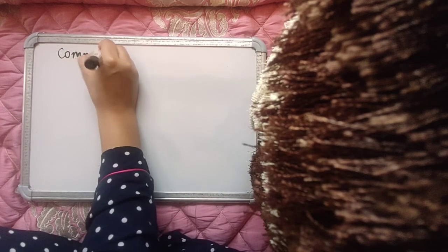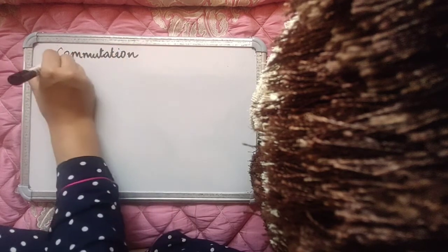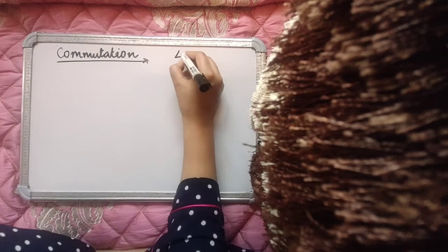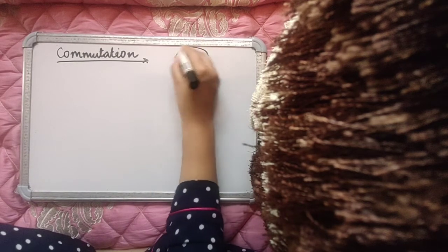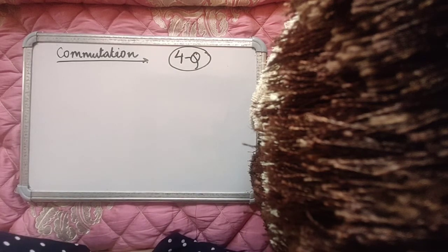Because commutation is a big issue when you talk about 4-quadrant switches or bidirectional switches. If you're using this bidirectional switch, which I just showed, that is a basic switching cell of a matrix converter, even if you're using it in some other converter, you are bound to face a commutation problem. Now, what is a commutation problem?